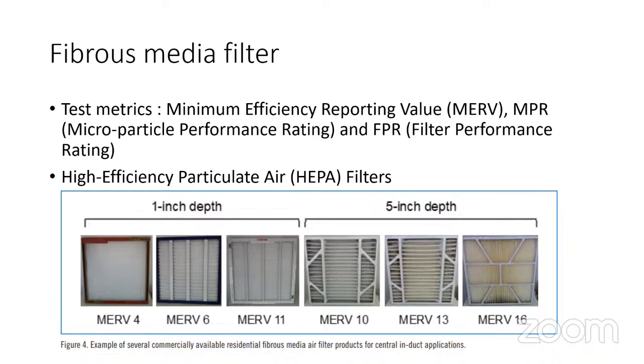So different MERV rated filters are shown in the picture. You can see that as the MERV rating goes up, the pleats or the pattern of the filter varies. And of course, the depth also determines the effectiveness. But when you increase the depth, there is an impact on the flow rate. So that will affect your CADR.